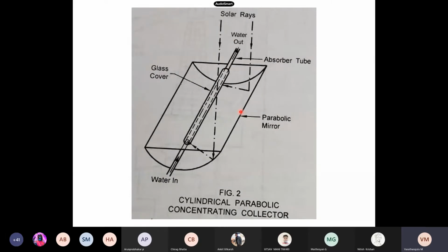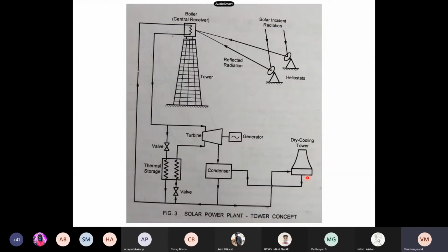Large parabolic concentrators are subject to large wind loads, and hence they require very strong supporting structures. For this reason parabolic collectors are not used for solar power generation, and an alternative to steering the concentrator is to use large flat plate mirrors. The cost factor along with the advantage of the fixed working surface makes flat mirrors common in modern parabolic solar collectors.